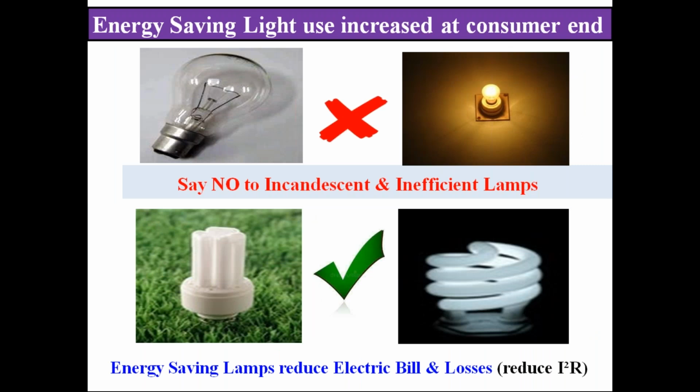The other thing we did, not-running analog meters were changed to digital meters. And the best thing was that 3-phase industrial meters were regularly checked almost 3 to 4 times a year. And we had all our meters, whether industrial or domestic, outside the premises. It had two advantages: if the house is locked, our meter man cannot go and read the meter, and pilferage percentage is also there.